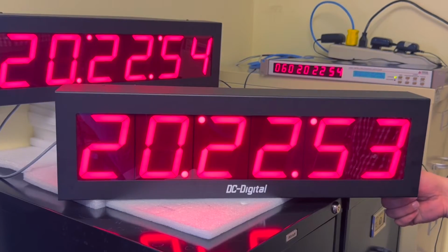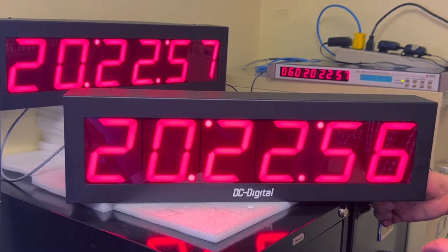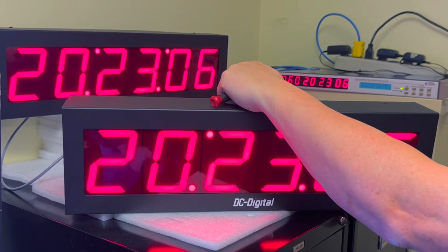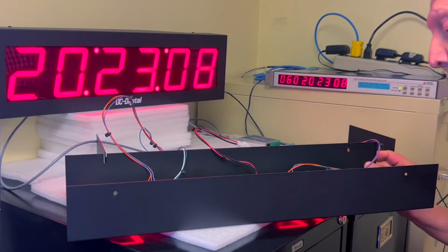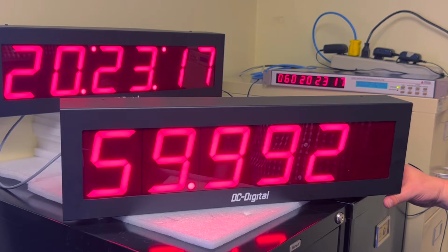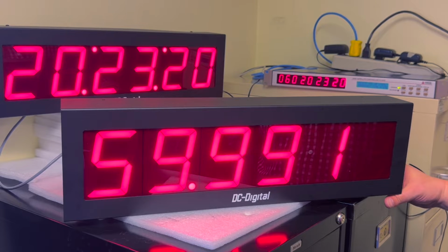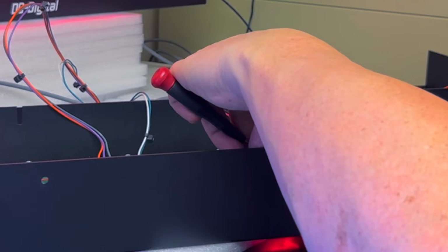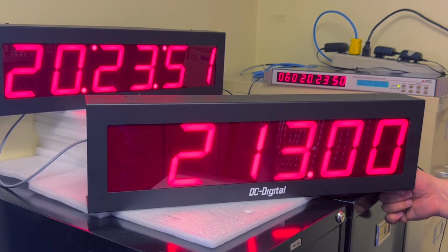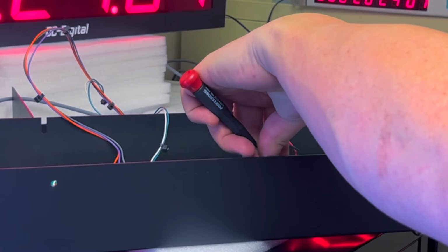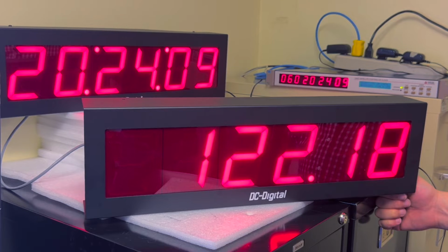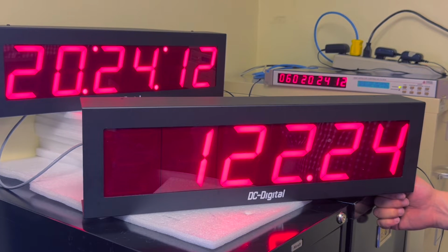Mode 6 is another time, and this is actually the system time. So this is the UTC plus or minus the seconds deviation. That's mode 6, address 66 in their application note. Mode 7 is the system frequency, so we are operating under 60 Hertz exactly. Mode 8 is the system phase, so this is 211 degrees out from 0. And mode 9 is the amplitude, so 122 is our sine wave amplitude on our power outlet.